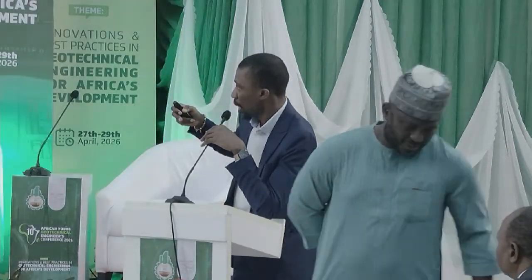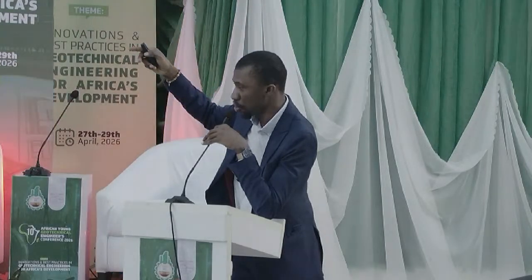Then after constructing the embankment, I am going to apply a vehicle load. I am doing this in half symmetry. It is possible in practice to do the analysis in half symmetry to reduce the analytical resources. A typical road has a width of 7.3 meters, so I just use half of it, which is 3.65 meters. Then I apply a vehicle load on it, which I represent by the arrow pointing down.